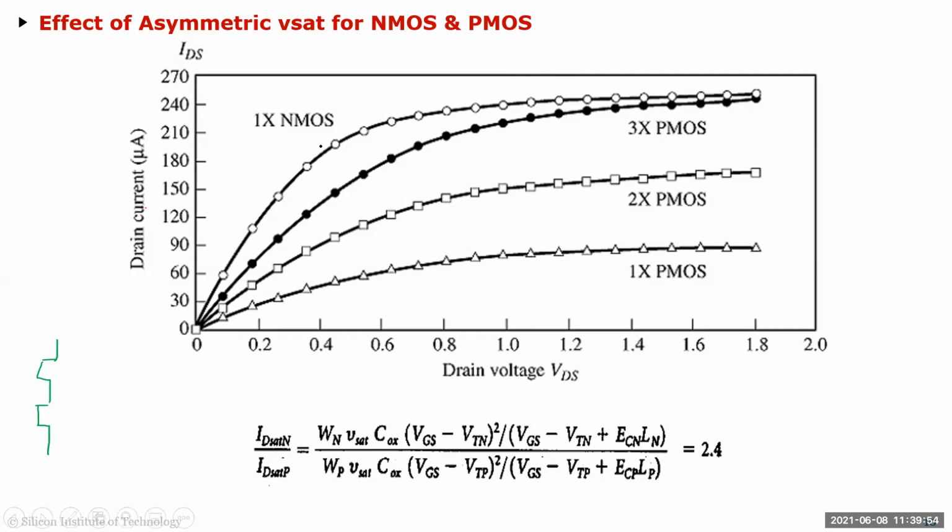There's a question from Ashwini. Can we convert each terminal into SI units for calculation? I mean, how to simplify the calculations? Well, I showed you, right? Instead of going through the units, just make sure the units are canceling. So if you have one in centimeter square per volt second, then have the other one as farad per centimeter square, instead of having farad per meter square and converting meter square in each one of them. Always have units which can cancel easily, and that's the way to do it. And that's what I showed you.